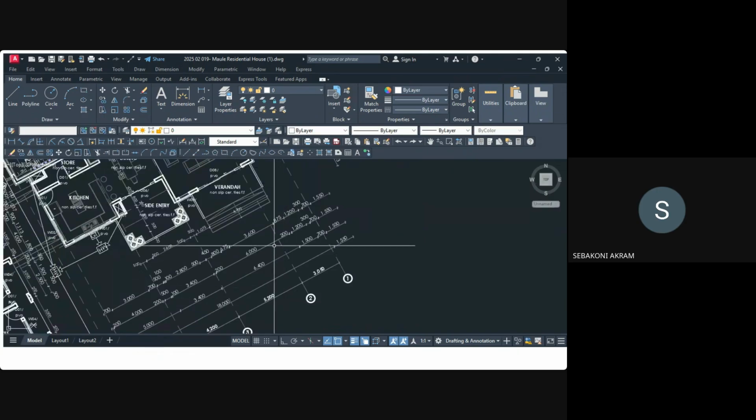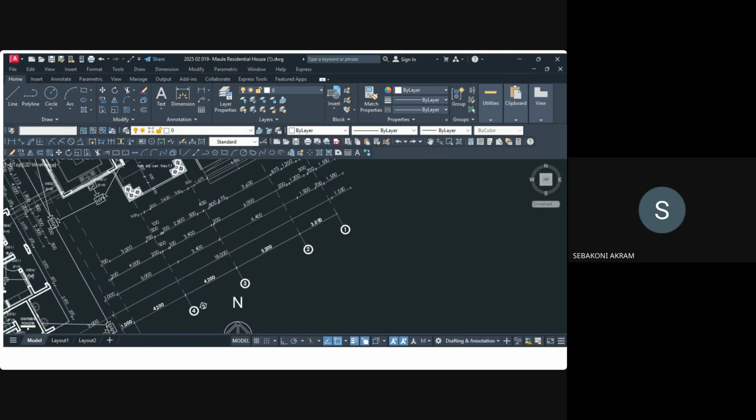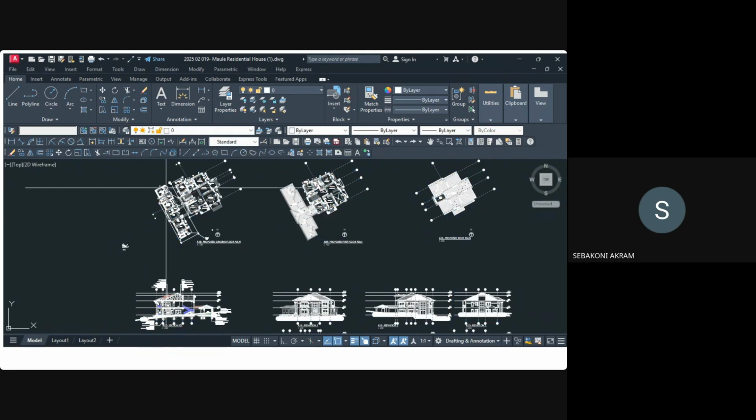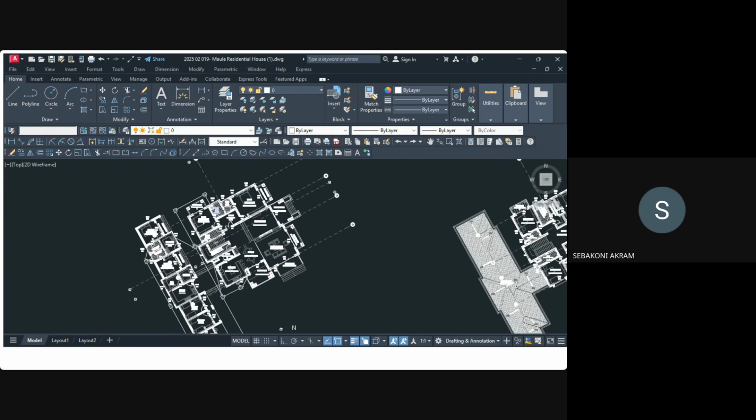So we would first start by cleaning the drawing, as you see. Let me say these are dimensions. You highlight them, come to select similar, because there are a lot which are similar to them. You've highlighted one at a point, so you can delete that. So you see how our drawing is becoming more clear.